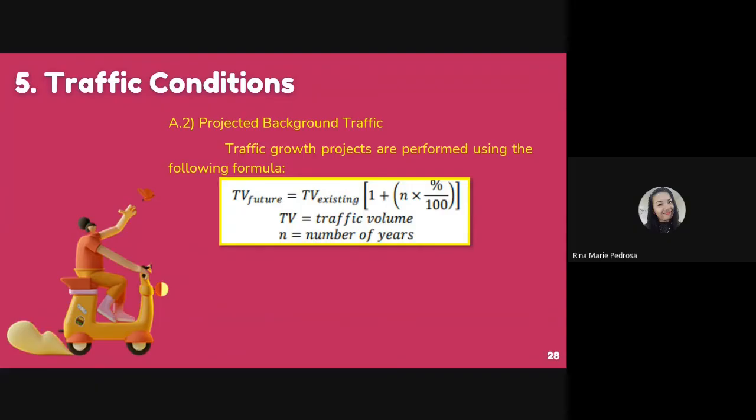As traffic growth rate is dynamic, different growth rates may be used for different development horizons in order to simulate the traffic growth trend. However, justification must be provided. Although traffic growth rate varies for every section of highway, the average annual non-compounded growth rate on the provincial highway network is about 1.5 to 2% from year to year.